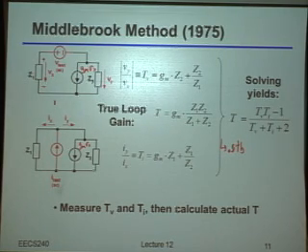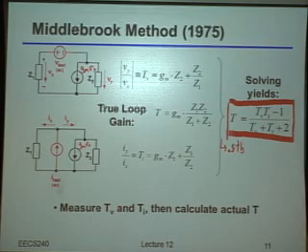The only other thing that I want to mention just briefly here is that, at the end of the day, the way I'm calculating my final loop transfer function is I have to do some math on two quantities that I measured. In particular, I have to multiply together these two loop transfer functions and then subtract one on the top. So here's where you have to remember that SPICE, and pretty much anything else you do on the computer, always has only a certain degree of accuracy associated with it.